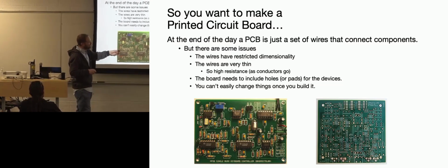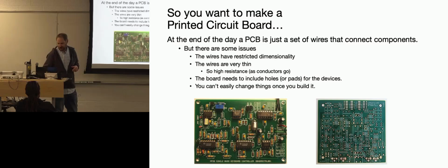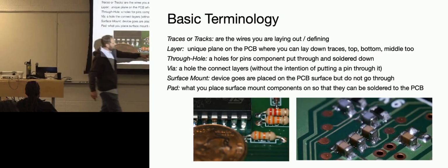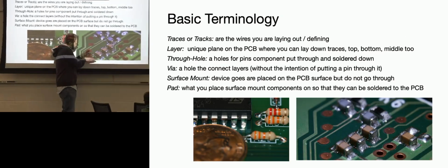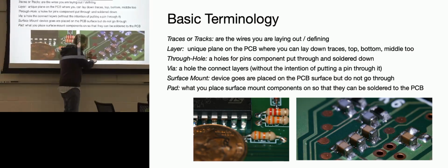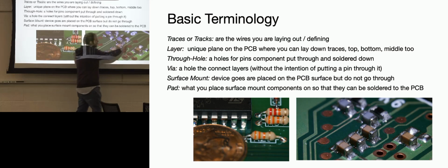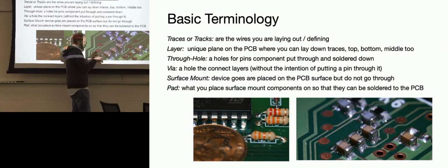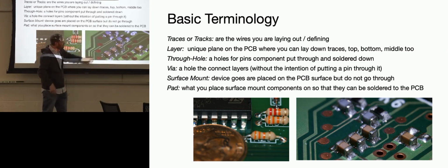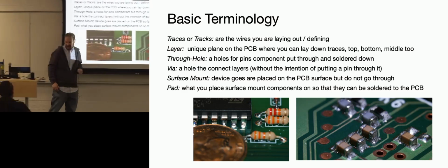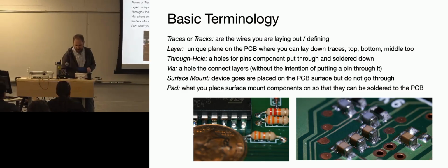So that's why these are cheaper electronics typically than surface mount like these, because with these, you have to place everything down, and you have to put the solder paste here first. Solder paste is just small particles of solder in a suspension, and it makes this little paste. You would put it down on a pad using a screen, like a silk screening process. And then you put your parts down on it, and then you put that whole thing in an oven. That's just much more time consuming than this task. That's one of the reasons those things cost more.